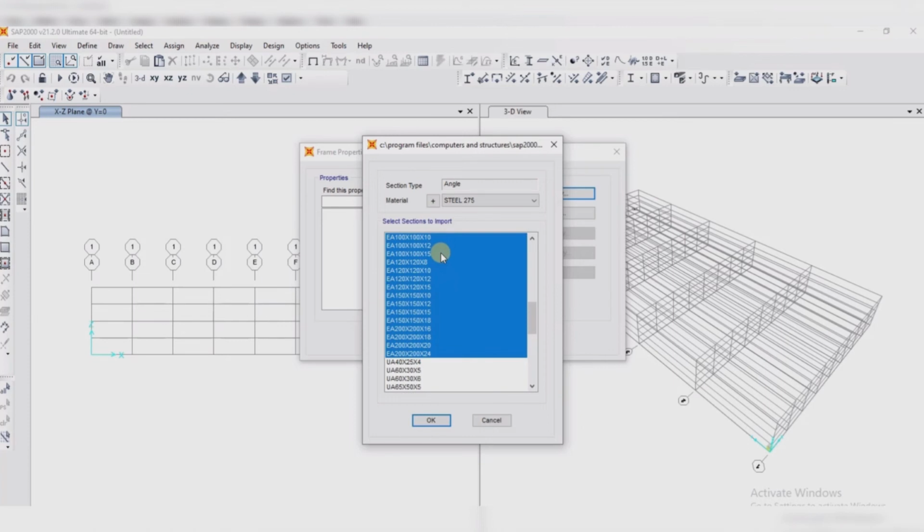For example, if I don't want to go through that, I can easily choose one section here. If I know that that section will carry the whole structure, I'll choose one section here and I will use this to model my structure, my steel. Once I do that, even though the force in that section is 200, since I've assigned that section on it, the section will still remain there. What I will just see is a warning that the section has failed. I need to change it. But it is very good to always make use of auto.